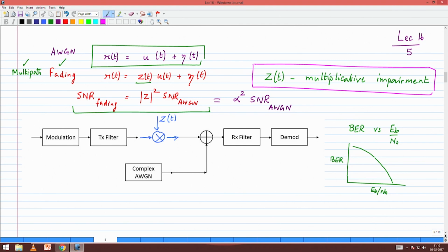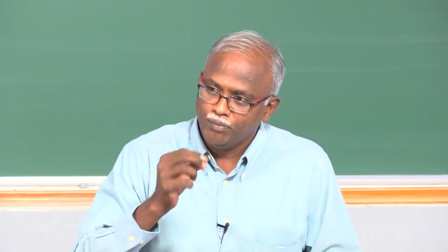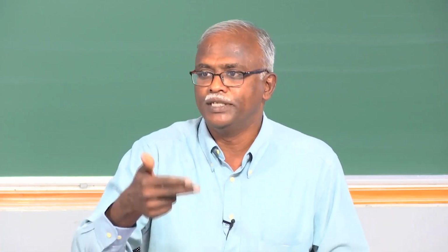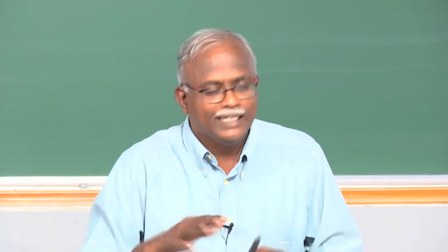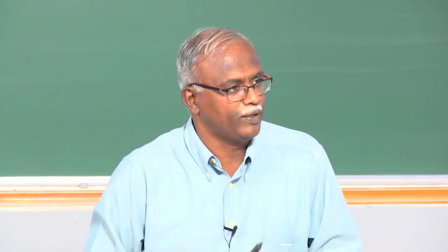And we showed that there are some points where the Rayleigh fading can go quite deep, which means that your SNR can momentarily go very low. So there is an impact on BER. How much of an impact? How do we overcome that? All of that is what we are going to study in the course. But is this basic notion of what happens when we move from an AWGN environment to a fading environment reasonably intuitive and comfortable to everyone? Any questions?